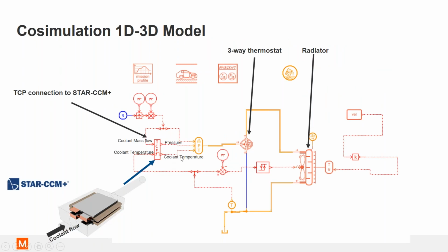Here we have a battery system in an electric vehicle. The radiator is basically responsible for cooling the fluid that comes from the battery system and is fed back into the battery system, and you have a given velocity profile of the car. So based on that velocity profile, the radiator is going to have some sort of cooling profile, which then defines the cooling system in the battery.